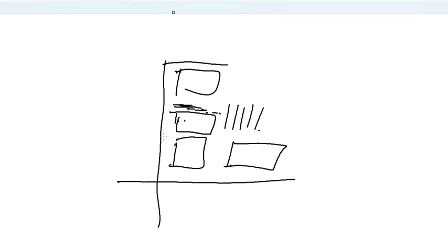So once you do this, you have a PR boundary ready for it. Thereby you will get an idea that, after I do the placement, matching, and use the dummies and the guard rings, I mean, you don't have to be too liberal as well. Keep something decent, with a little spacing in between for you to route the signals. And then you can come to a conclusion that this is the area my module will take. And don't give the estimation without adding the guard rings or dummies. It'll hit you back very badly.